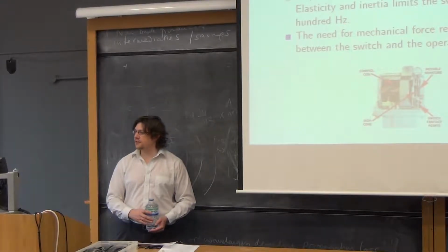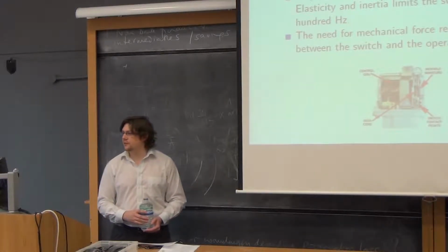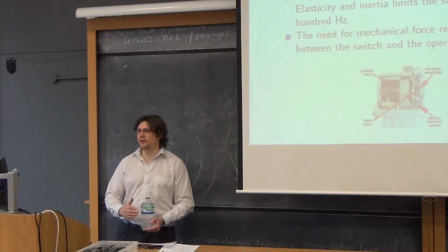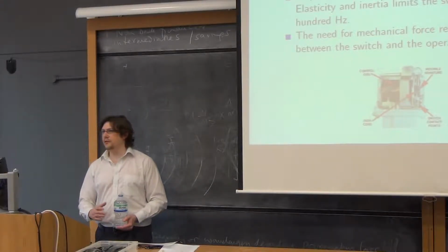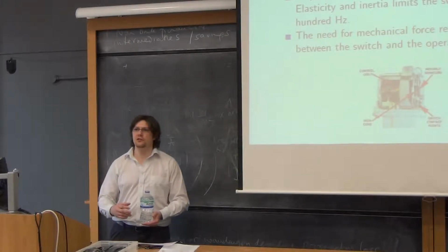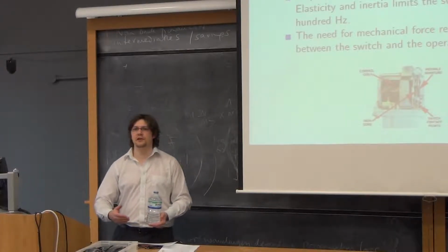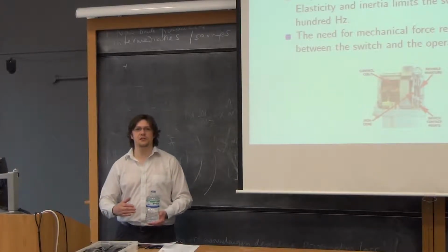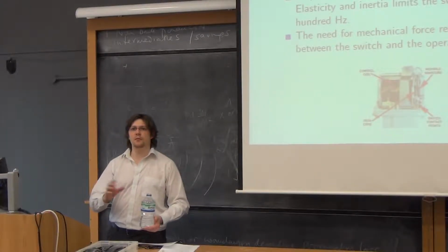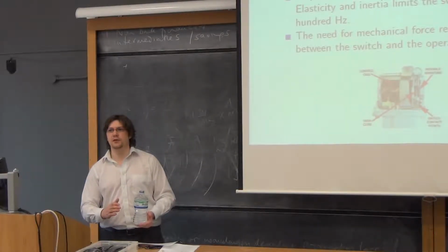So mechanical force brings together two metal contacts, and these are easily designed for currents in the range of a milliamp to about 10 megaamps. Above 10 megaamps things get very tricky, and below a milliamp, after a long time the contacts tend to oxidize somewhat. Then if you open the switch and close it again, you can find that the contact isn't nearly as good as it used to be. Similarly, when you're closing an enormous current, there will be an arc beforehand, and that arc will oxidize the switch surface, and then there will be some difficulty making the contact.